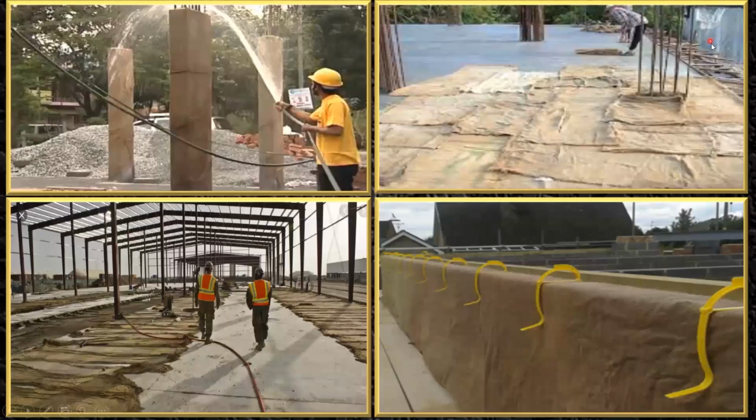How does it look? This is how we do it. We can call this a gunny bag. If it is a bit thicker, then we call it jute matting. And hessian cloth is also the same thing. Here we wrap the column, and once you sprinkle the water, since the cloth is able to absorb the water, the water will remain on this cloth for a very long duration of time. As a result, you don't have to keep on spraying the water every now and then.